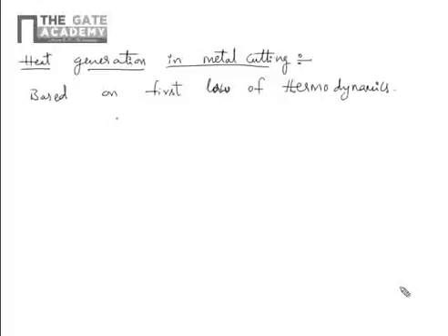Heat supplied here is in terms of power supplied to the tool. So power supplied is work done by the tool, as well as heat generated, internal energy. Here the heat is generated at different zones: between workpiece and tool, between tool and the chip, and between chip and the workpiece. So there are different zones. We need to discuss how much heat is generated at each zone.